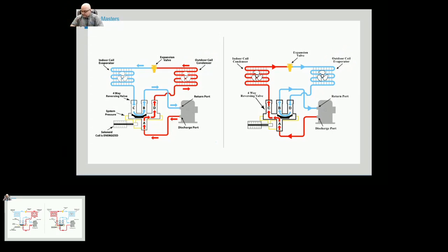So indoor somewhere. Now, that's the first thing. Secondly, so the first thing is naming the coils as outdoor coil and indoor coil. Okay. Secondly, we need to understand that the direction of the refrigerant flow is going to change or reverse.